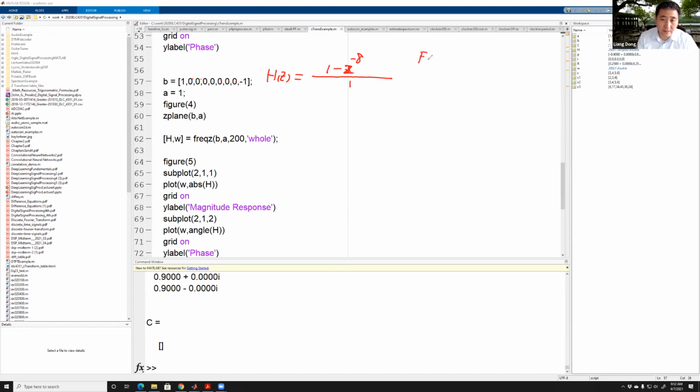It's an FIR system, finite impulse response, because I don't have feedback. So all you do is take the input convolved with my filter, which is just 2 parts. One is itself, a delta function. Another delta function is at delta n subtract 8. You have a delay. So the entire impulse response has a finite support, meaning that over finite time you get non-zero values. So it's an FIR filter, easy to implement.